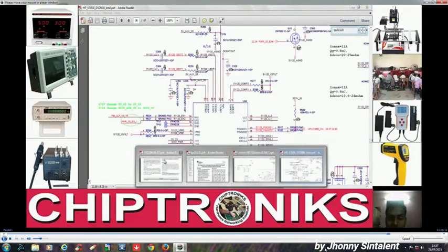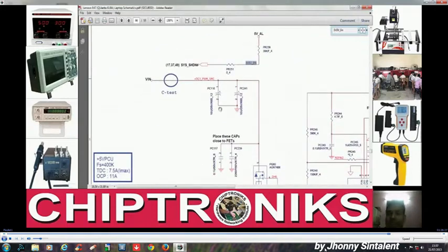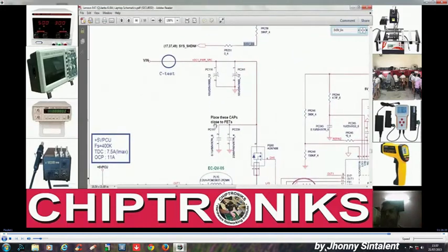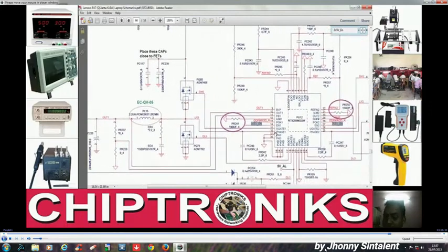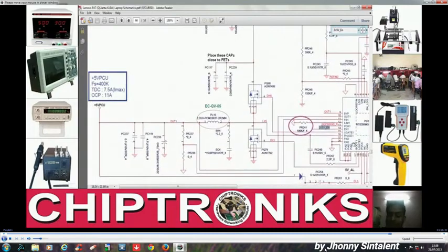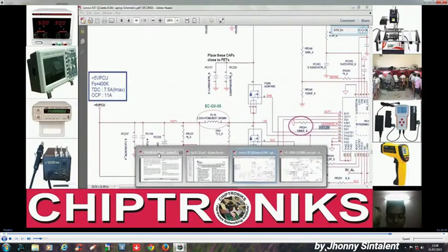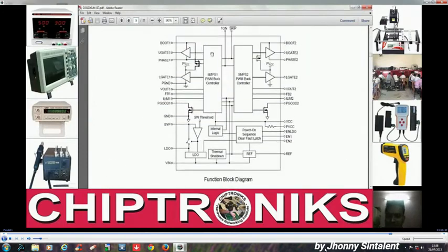whereas in Lenovo Y470 or 570 we have no such thing. It is internally fed. That is, this IC will generate the switching voltages. Once it gets Vin and enable LDO, this will generate the switching voltages. This SMPS inside the RT8206 will get started when it gets Vin and enable LDO, right?